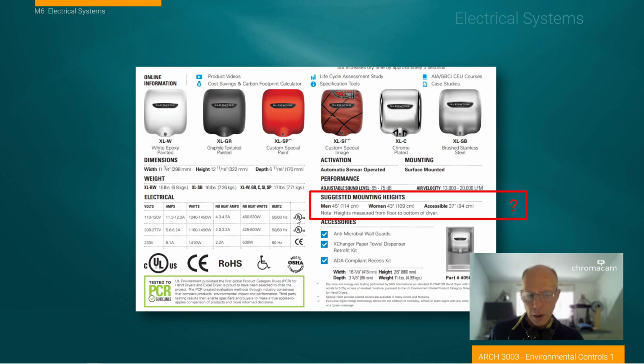And then this last one I think is really important, and this is code approval. So this is UL, Underwriters Laboratory, and the one down here is the Canadian standard. These are codes. When a device has one of these stamps on them or approval, it means that it's an industry standard for acceptability and safety. Without one of these stamps, it would be likely that you wouldn't want to install that appliance, or an electrician would not want to install it. So we're always looking for these code approvals, especially when we're looking at new equipment or unusual equipment that we might want to specify.